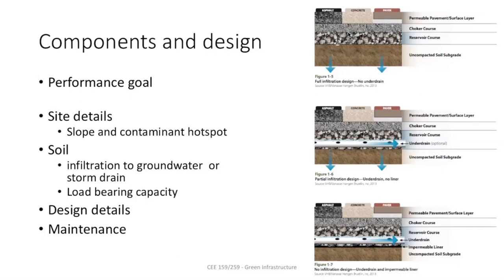Then the third constraint is about infiltration. This design short-circuits the surface flow to the subsurface, but the water has to go from the surface too. For that to happen, you have to have enough storage and some infiltration capacity into the ground, or some kind of conveyance system where water can be discharged from there to other places.